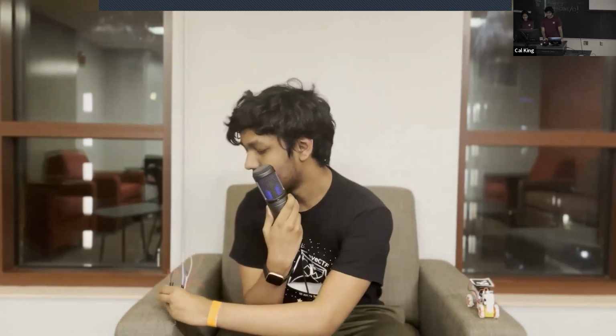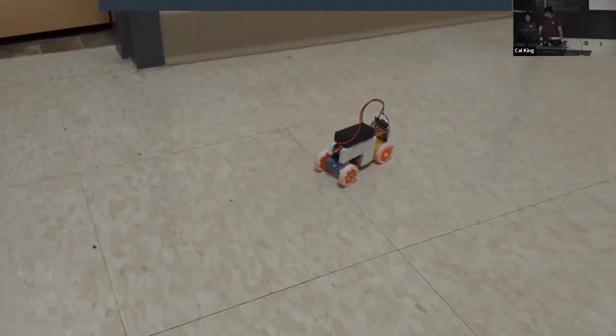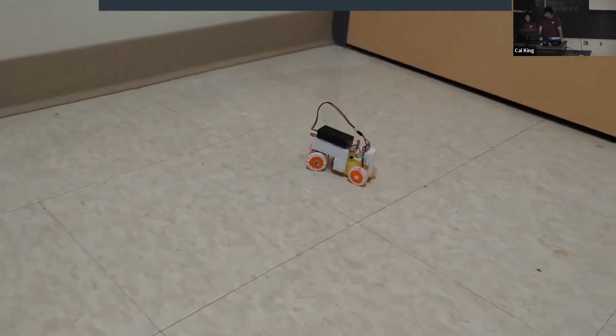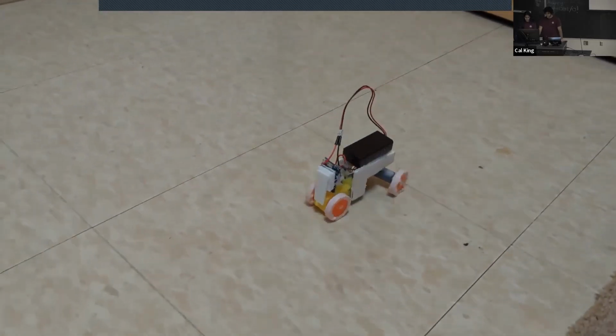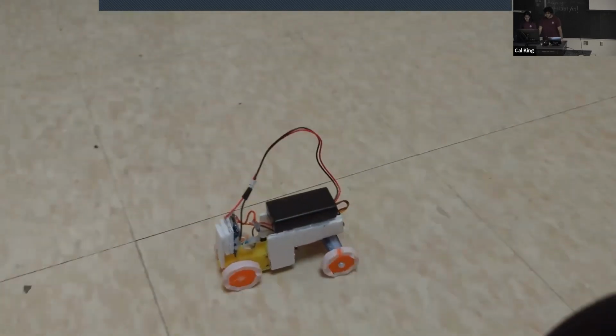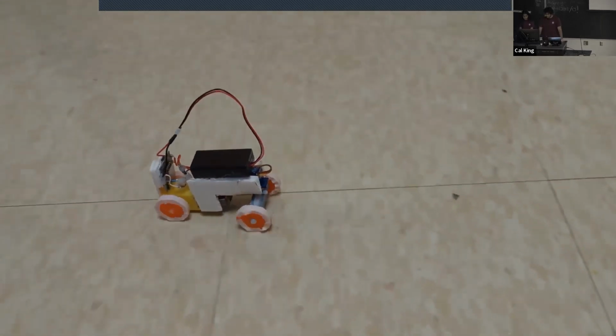We started off by drawing out a circuit diagram. This would be basically everything that would drive just the main motor itself, without rotation, which we handled with a servo at the back of the vehicle, because our first prototype, we ended up putting the motor the wrong way, and we decided to just stick with it because it was easier than undoing all of the hot glue that we had used as insulation and redoing the other robots as well. So we have front-wheel drive with rear-wheel drive steering.